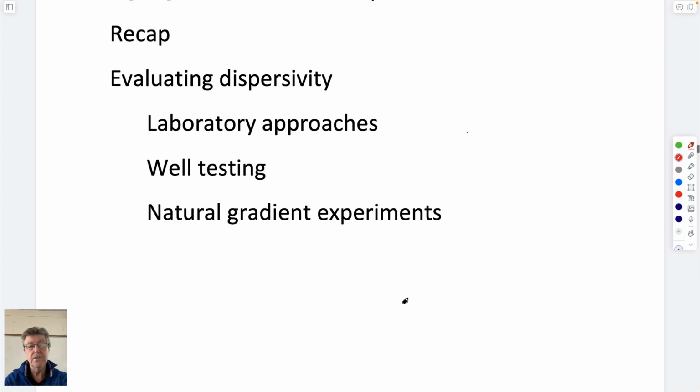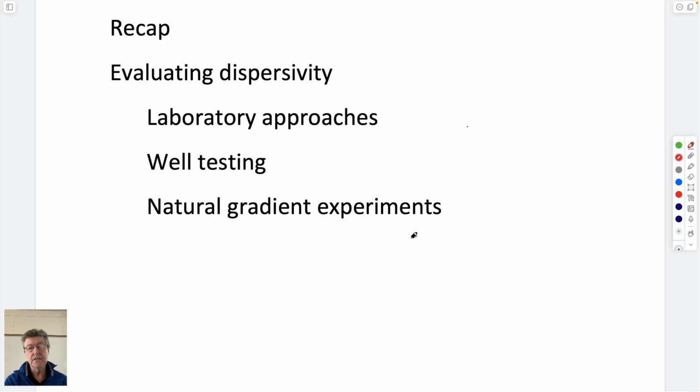And so perhaps it might not be terrible to write it down. It's something that is change in concentration with time, I guess these are partials, is equal to longitudinal dispersion, change in concentration in the downstream direction, minus advective velocity, actually I'll write the other one first, plus transverse dispersion, change in concentration across the flow path, and minus the advective velocity dc dx.